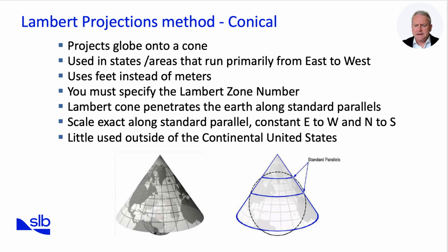The lesson here is to always verify projection parameters before integrating data. Even a small mismatch in zone number or units can create errors large enough to compromise well placement or asset mapping. The Lambert projection is precise within its zone of application, but like all projections, it has limits.